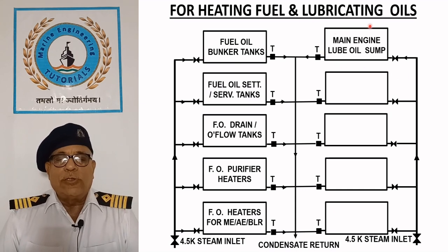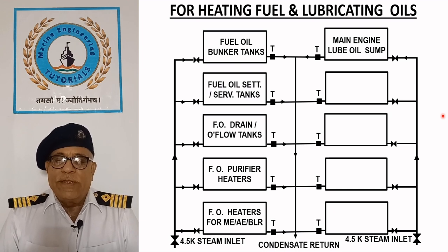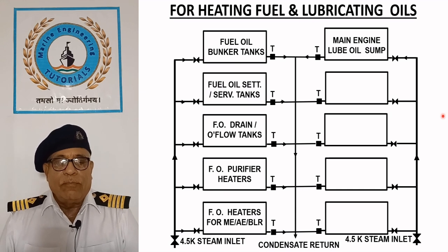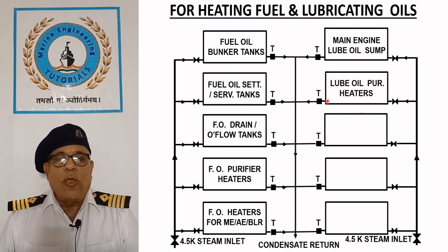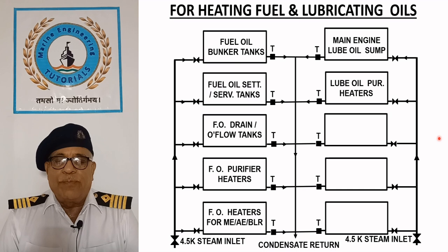Main engine lube oil sump. Lubricating oil in the main engine sump may be preheated to about 40 degrees Celsius before starting the engine after prolonged stoppage. Normally, the oil is kept warm through the continuous operation of the purifier. Lube oil purifier heaters. Before purification, lubricating oil is preheated to around 90 degrees Celsius, which enhances water separation due to increased density difference.